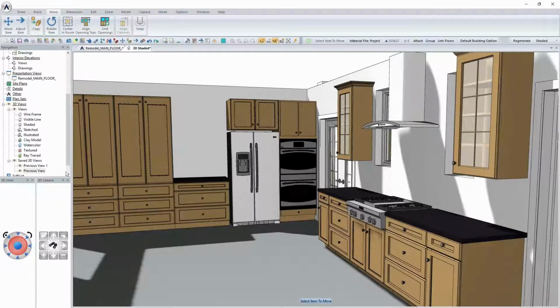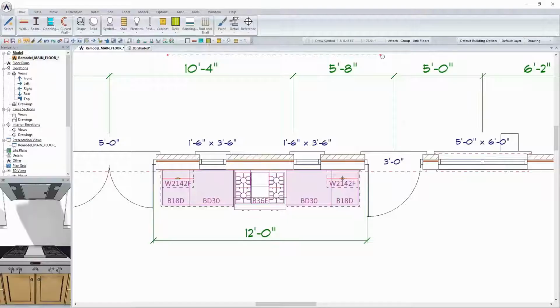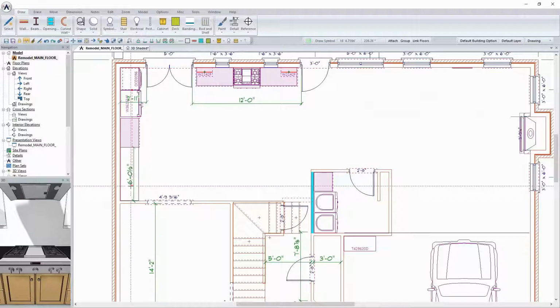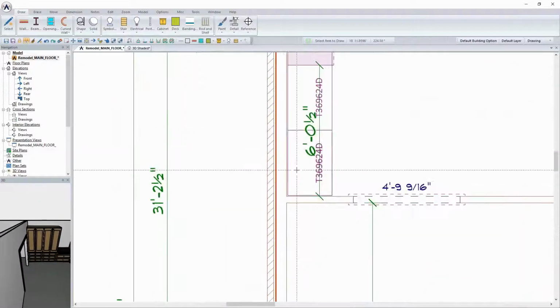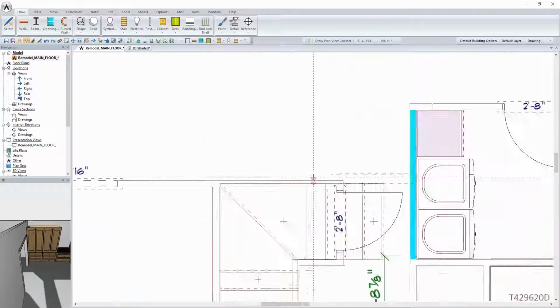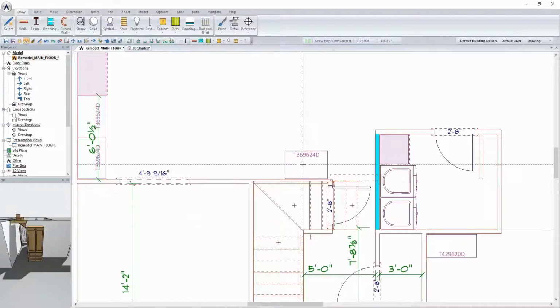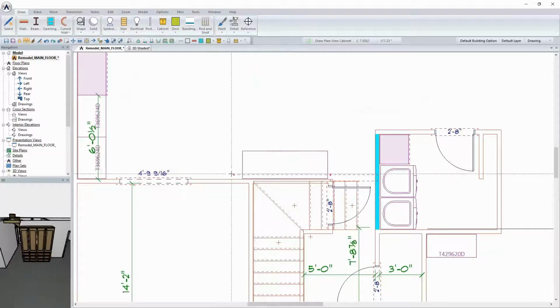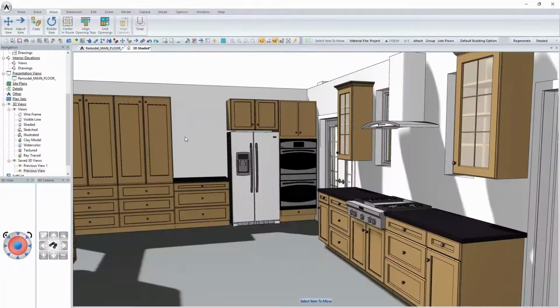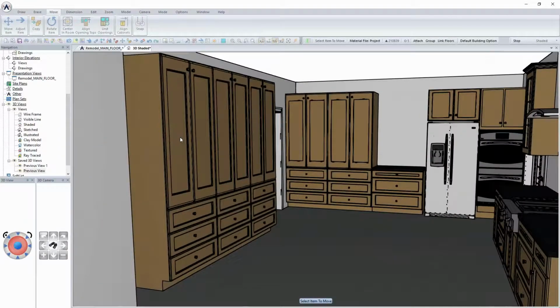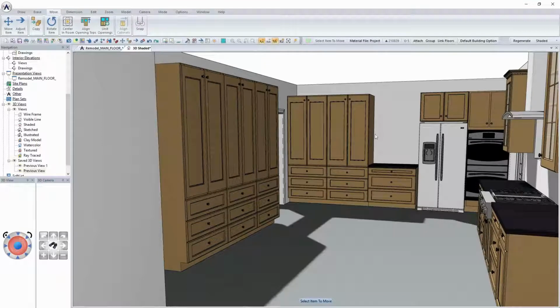Okay, so the back wall is in and the cabinets are built. This has been built over here, the range hood, as well as the custom cabinetry and so on that will be needed for the gas grill. I'm going to come in and, using draw select, pick this cabinet right here, and click to insert one right there. This dimension from here to here, I could certainly spec out. I'm just going to draw a bank of cabinets in for right now that's going to run along that side of the plan, and save it for now, and set ourselves up for placing an island in here.